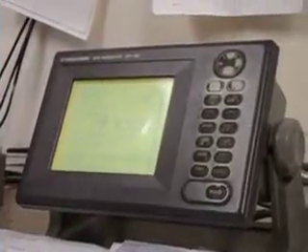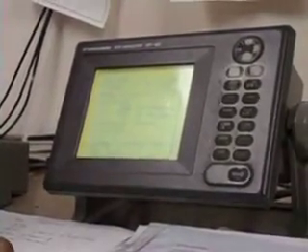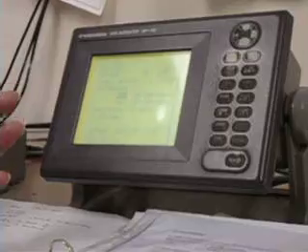For speed smoothing 005. Now when my ship moves, the antenna also always moves a little bit port and starboard due to rolling and pitching, forward and aft. So as the distance from the satellite and the angle change, this machine thinks we altered course 5 degrees starboard, 5 degrees port, 5 degrees starboard, 5 degrees port. Too much rolling, 10 degrees starboard, 10 degrees port. If it is pitching, then it sometimes shows speed 12 knots, 11 knots, 12 knots, 11 knots. So it becomes confused. To average out, they have given some value.